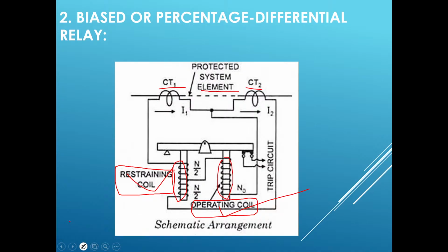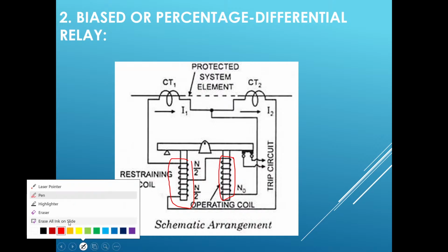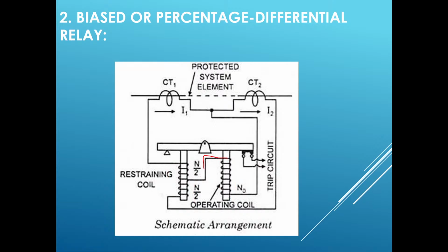So this is our restraining coil, this is our operating coil. If you carefully observe here, the operating coil is connected to the midpoint of the restraining coil.